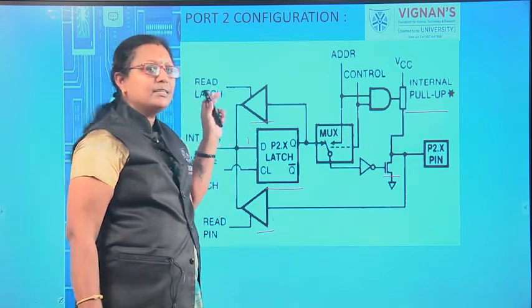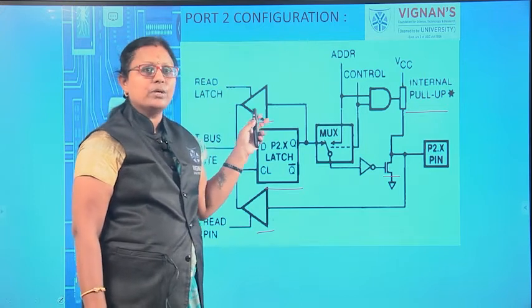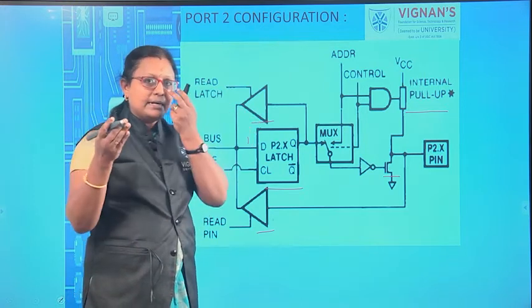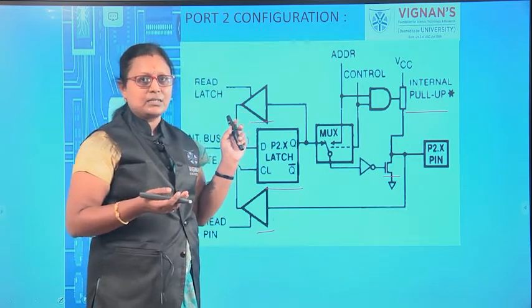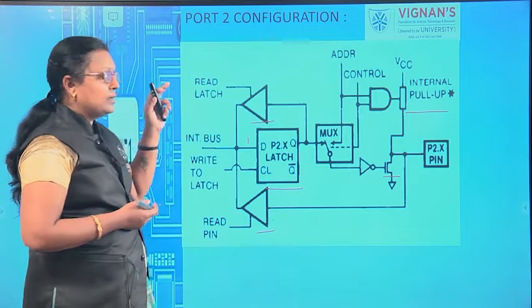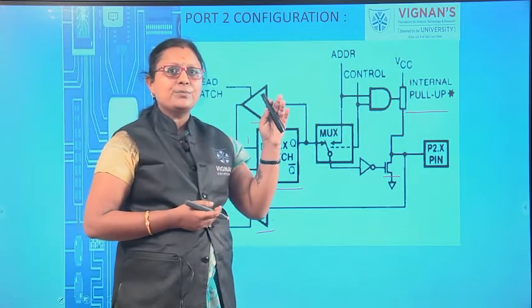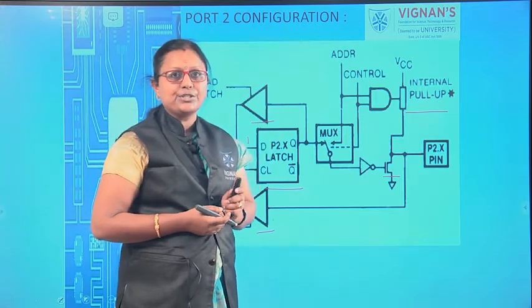And I told you that this port 2 is used for higher order address bus signals. So, that is why A8 to A15 has to be accommodated with port 2 configuration, okay.